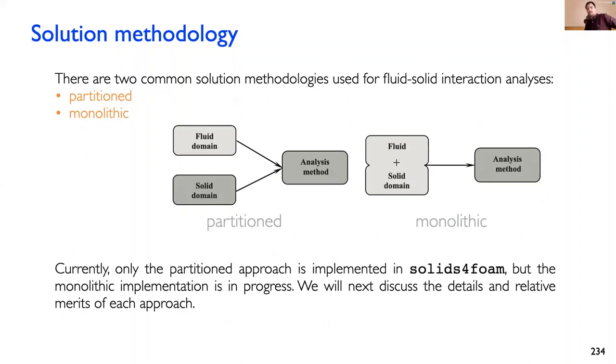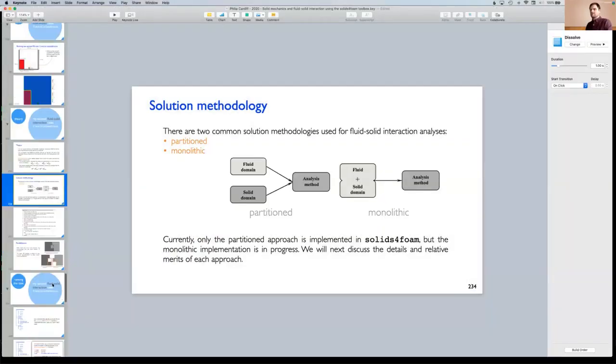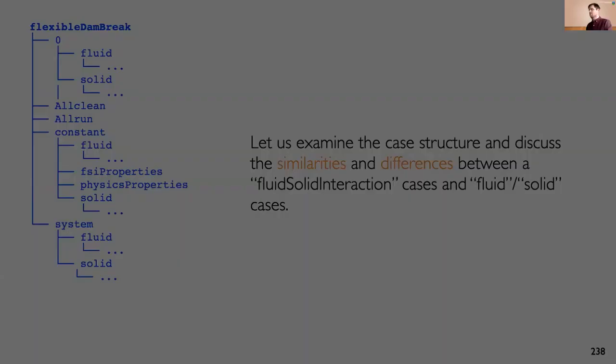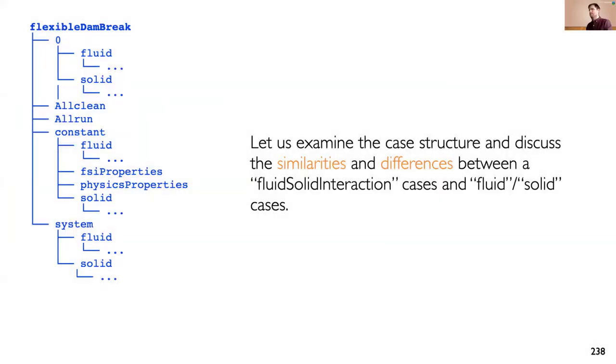There are many different FSI type procedures. Well, 2 predominant ones. Partitioned is the most common one, where you solve a fluid case and then you solve a solid case and you pass information between them. It can be done monolithically, and it has to some degree in OpenFOAM, but I would say those procedures would need some development to make them generally useful.